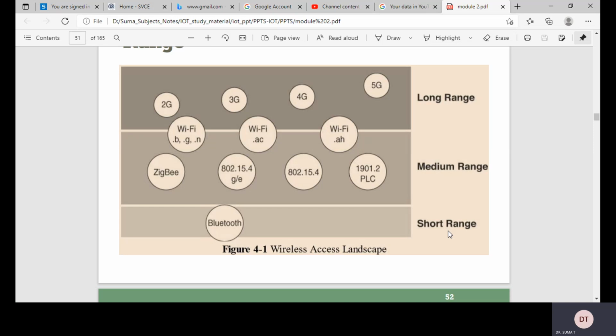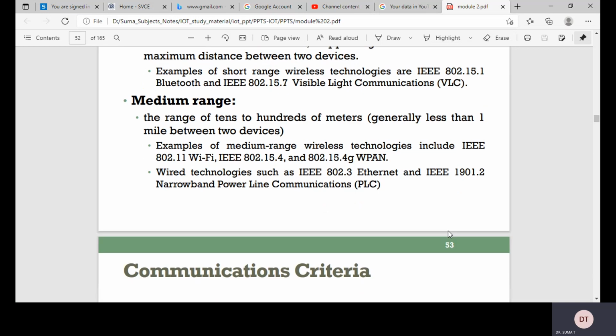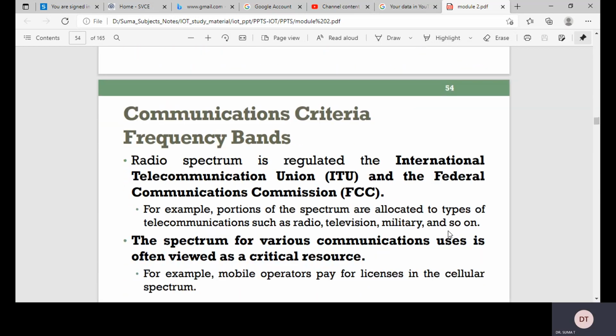You also need to consider environmental factors such as interference and noise, and specific product characteristics such as antenna design and transmit power. Finally, you should be aware of potential landscape and topology changes in the field, such as new buildings that may interfere with the signal transmission. Okay, so that is about the long range.